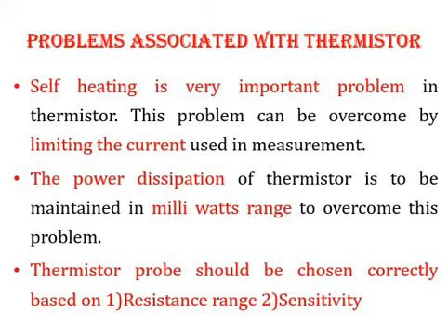When current starts conducting at the ambient temperature, there will be a power drop in the thermistor, power dissipation, in terms of milliwatts. How can this be overcome? The thermistor probe can be chosen correctly, considering first the resistance range and sensitivity. These are the points to be considered for the problems associated with thermistors.